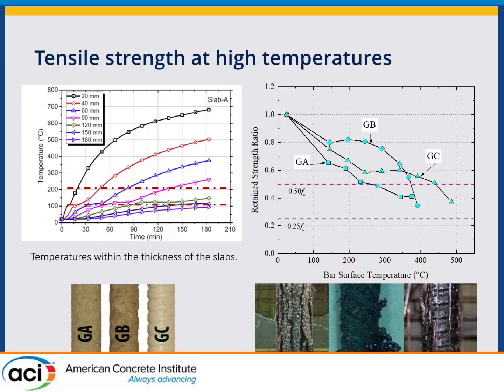And you have to remember what we did. In a fire, it's this idea about combinations of events. We design for an extreme event when you might have a really extreme load on a structure, and so you will need most of the strength of the reinforcement in that case. However, in a fire, you don't expect that you will also have the largest load. Generally you won't, because if it's people, they're going to be leaving. Let's hope. Hopefully all the people can be evacuated before we have to worry about structural integrity.